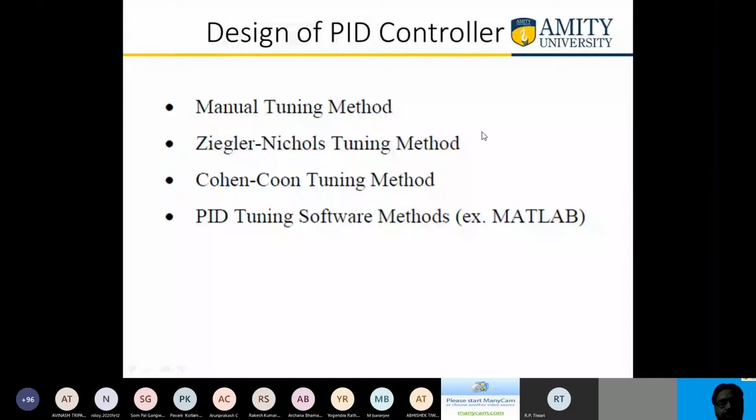Okay. So what we have done till now is some manual tuning. We are changing some values and observing the result. Practically, it becomes very difficult mathematically to do it with paper or pen. So we have better methods, the Ziegler-Nichols method and the Cohen-Coon method. Of course, Cohen-Coon has a limitation that it works only for first order systems. So Ziegler-Nichols is more popular.